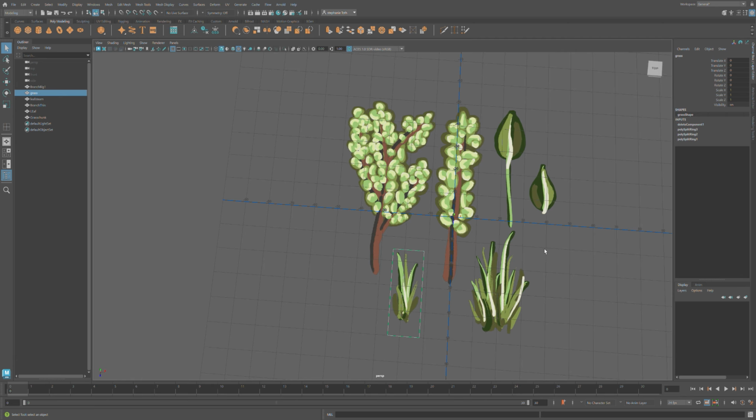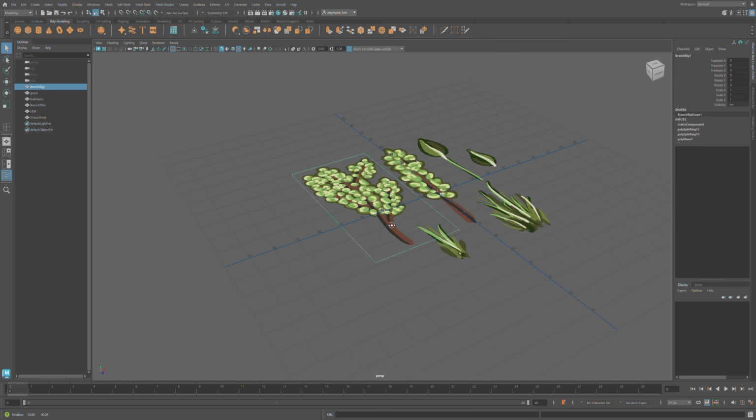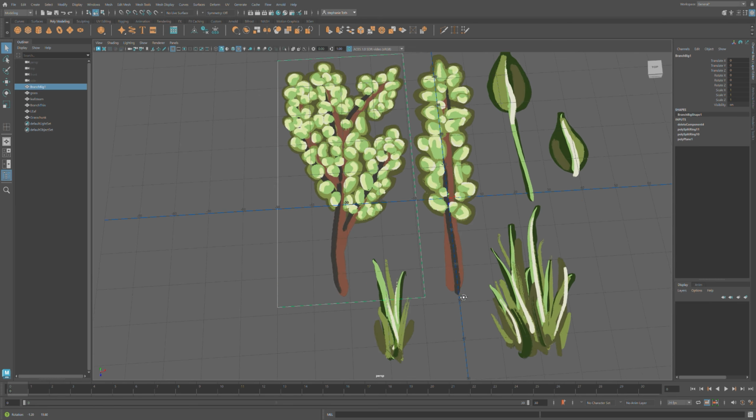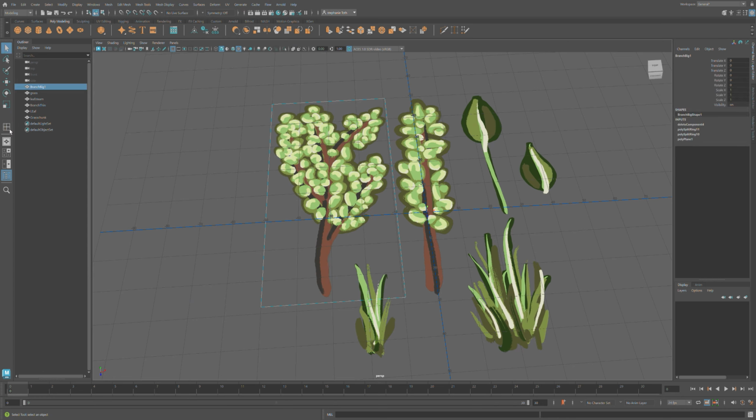And now I just need to add in more edge loops so that we can actually fit it to the aesthetics. So I might send one right up the center and we'll just add some throughout. And then we can edit the topology more. So I'm just gonna delete these empty spaces and we can even move the vertices in. Notice how this is not affecting the texture at all because we kept preserve UVs on. So we'll just do something generic like that.